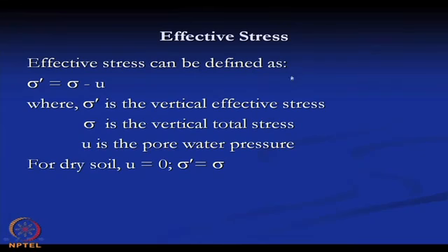So, the next concept is the effective stress concept. Now, what is effective stress? Effective stress can be defined as the total stress minus the pore water pressure, where sigma dash is the vertical effective stress, sigma is the vertical total stress, and U is the pore water pressure.